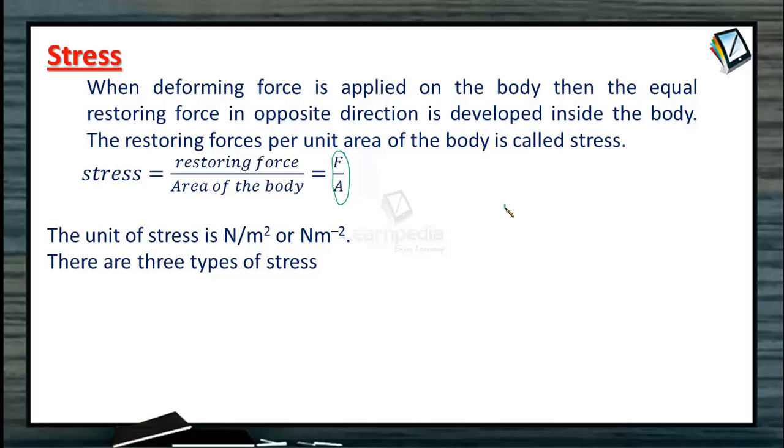For example, suppose here we have a rod and we apply a pulling force on both the ends of the rod. Then visualize one part of the rod here by cutting it mentally, and this is the other part. So here force F is there as shown, and this part is also experiencing the force F. As we know, in the whole rod the net force is 0, so it is not going to move anywhere. So the parts of the rod must also have net force 0.